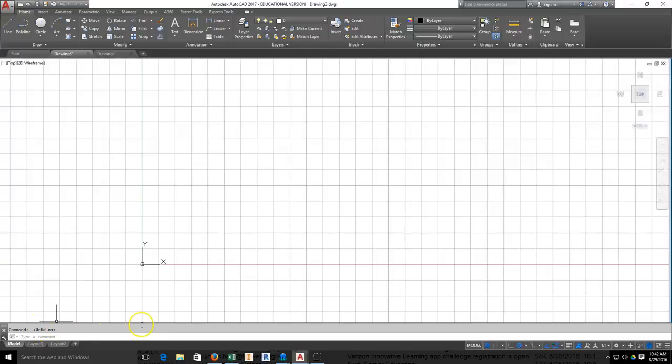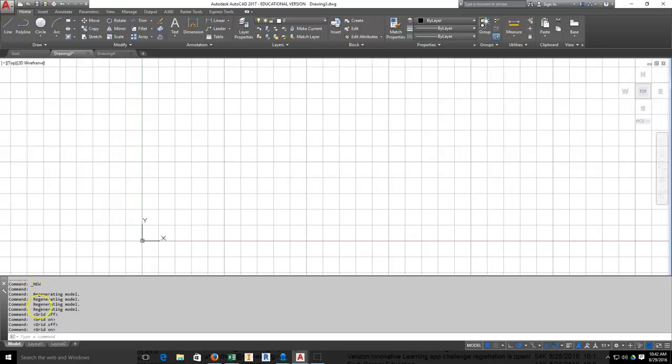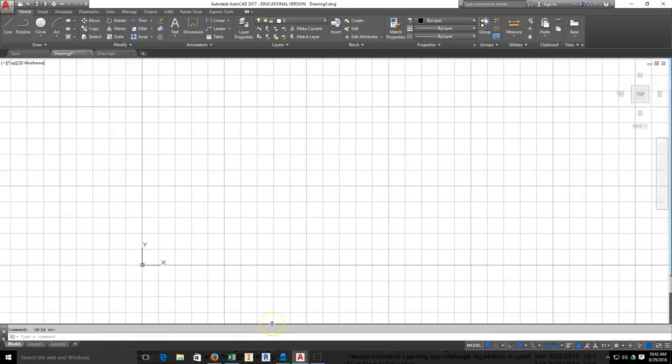You can also then slide your cursor up until it becomes an extend cursor, and you can bring the command line up and you can see past commands. You can get in to see legacy commands. The command line is how you actually communicate with AutoCAD. Working with AutoCAD is really a communication. You ask AutoCAD to do something, AutoCAD asks you, what do you want me to do? You tell it something, it asks you a question. And this command line is really the interface between that question and answer with AutoCAD. Okay?